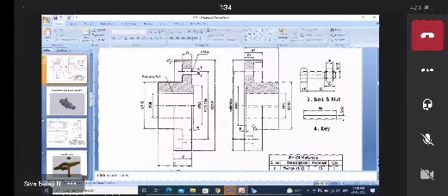You can check this in flange 2. For flange 1, the outer diameter of 4 mm is outside. For flange 2, 5 mm is given inside. In between these two, there is 1 mm tolerance, okay, for clearance. So you can give 5 mm inside here. That's why you can select here. You can check it here.